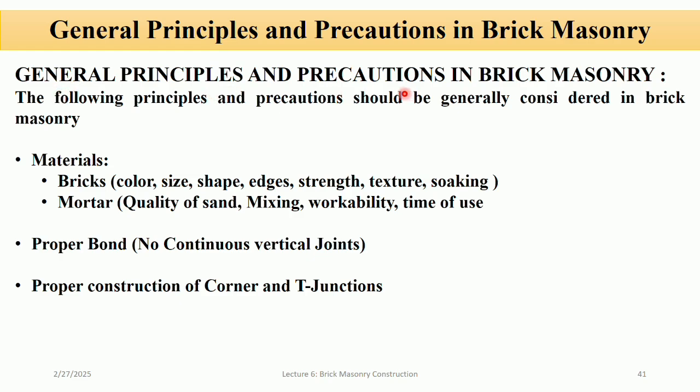General principles and precautions in brick masonry. The following principles and precautions should be generally considered in brick masonry. Material. First we have to check the bricks. Bricks to be used for masonry work should be well burnt and of uniform size, shape, edge, strength, texture, and soaking.